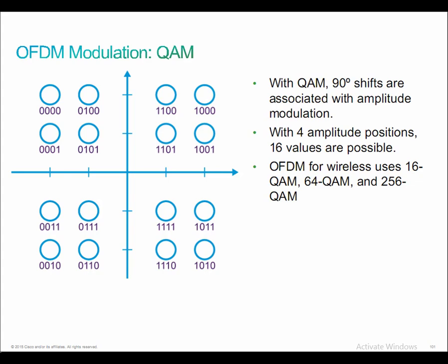Think of it as the horizontal plane and the elevation plane, although that's not exactly true, but that's the concept. If I hop from one direction to the other, that is essentially the principle behind QPSK and DQPSK. Because we're actually shifting the electric field or changing the orientation of the waveform, these techniques need new radios, new hardware, and they consume more power as well.